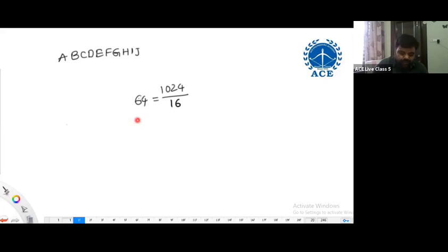64. The 64 4 to 16 decoders are using the last 4 variables as inputs. To enable the 64 4 to 16 decoders, I need to use 64 lines. To produce 64 lines, how many 4 to 16 decoders are required? 4.